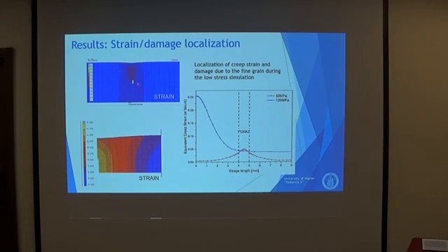And if we compare the same results for higher stress, you see a completely different strain accumulation, less localized. The same thing in this graph is reported in terms of equivalent creep strain versus the gauge length. So we predict exactly the total elongation and the location of the fracture.